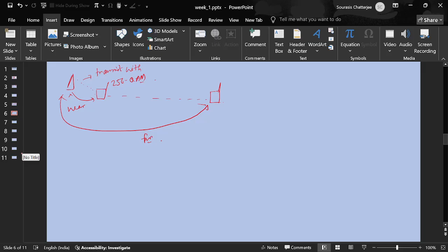You'll have high CFO because of Doppler. Yeah, so SNR will reduce, and then ultimately your MCS will also reduce. Correct, true. But the base station doesn't have this information yet. I am considering the hypothetical situation when the user moves quite fast.